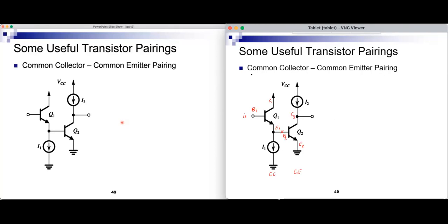If I'm using more than one transistor, I should get better than common emitter. In the case of MOSFET, the common source becomes the reference we compare to. If I'm getting worse characteristics, then there's no point in adding transistors. If I'm getting better characteristics, then that's an improvement over common emitter, and therefore we should consider this configuration. Okay, so this is common collector, common emitter.